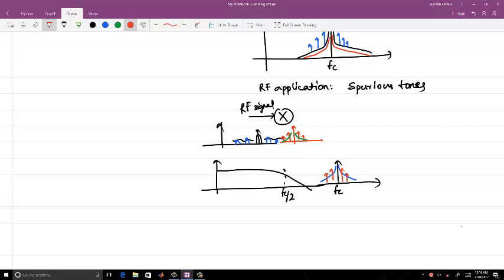Yeah, so that is down converting the noise, but you do not have a big nearby interferer or blocker sitting just at the spurious tone, which would make your signal lose all the sensitivity it has. This is the difference between designing a PLL for an RF case and for a broadband case.